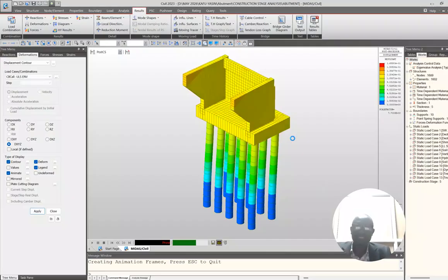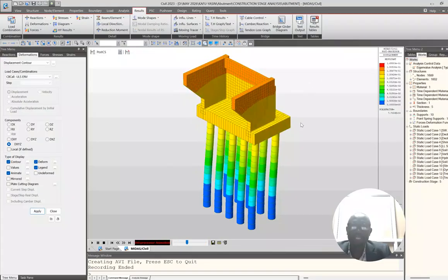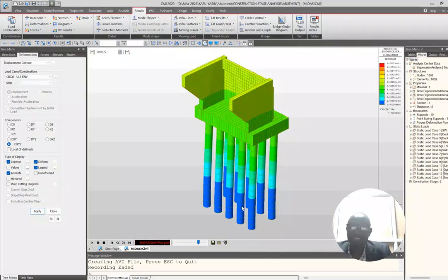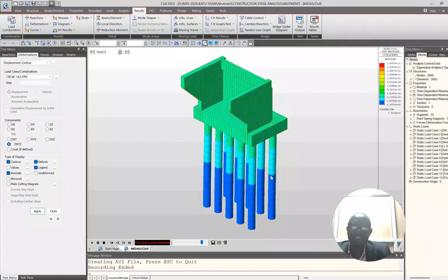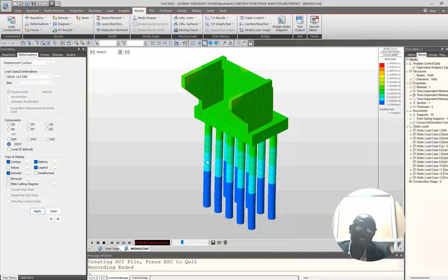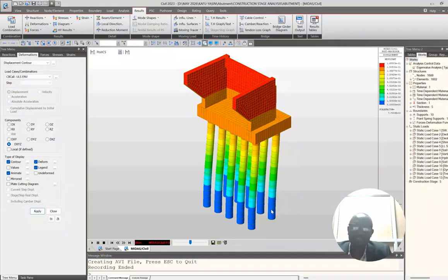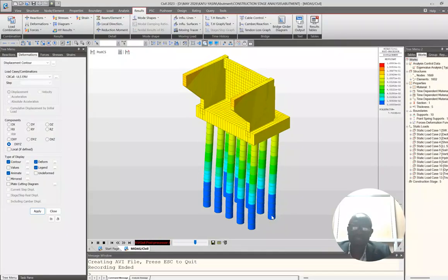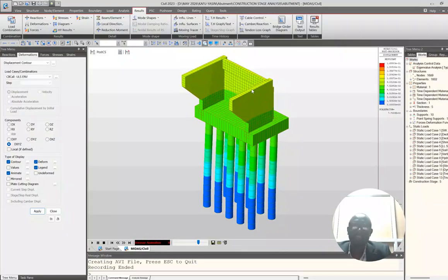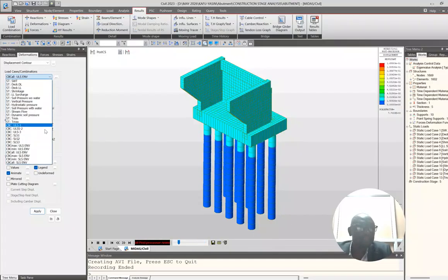And then there are things we need to look at. This one I have not applied; this is only when you have a push in the bridge's direction. So you have a push effect here and the pull effect. All that needs to be assessed during your design. You have to check all this, because this pile can actually tear, or there is tension here, while here is heavy compression. So you have to be careful. Sometimes even the bearing capacity may not be able to take it, so you check the push-pull effect.